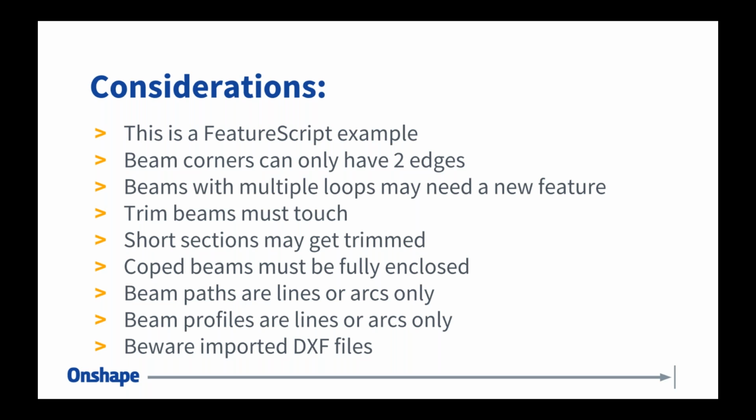And as I painfully am aware as of today, beware of imported DXF files. Make sure that the DXF files are fully enclosed. When you actually generate profiles, it's easy enough to test, so you can see the original sketch and reference it to the 3D model, and then be able to see if there's any issues with the profile.